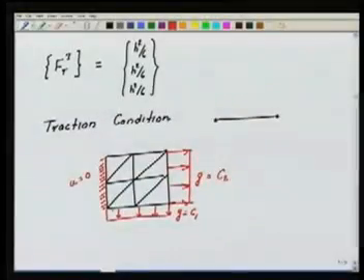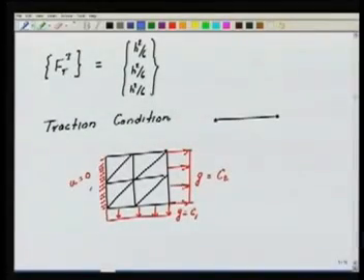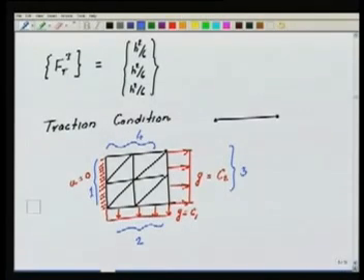So I am going to now identify these edges where the boundary conditions are changing. So I am going to identify two things as far as the domain is concerned: these distinct edges where the domain profile is changing, those things we have to identify. Also we have to identify the edges where boundary conditions are changing of one type or the other type. Here in this example we will say that this whole edge is boundary edge 1, this whole edge is boundary edge 2, this whole edge is boundary edge 3, and this whole edge is boundary edge 4. So we have 4 boundary edges in this particular problem. Okay, I will discuss further this issue, but let us take this particular case. Okay, so on these 4 boundary edges, now you see there are different types of boundary conditions.